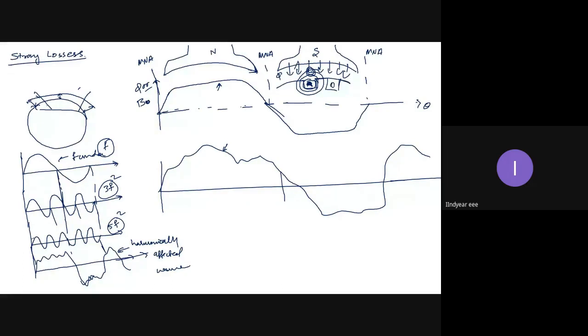So we have this conductor. This is the armature. This is the slot where conductors are kept. This is the teeth. Now this teeth, which is an iron part, is subjected to this non-uniform flux wave, so there will be a non-uniform EMF induced in this teeth.